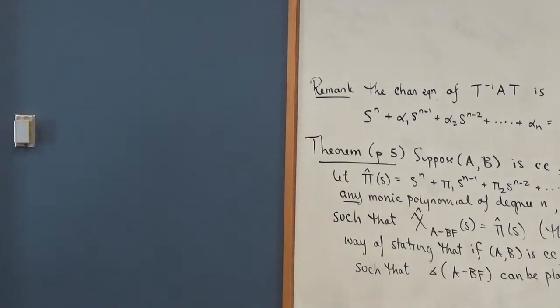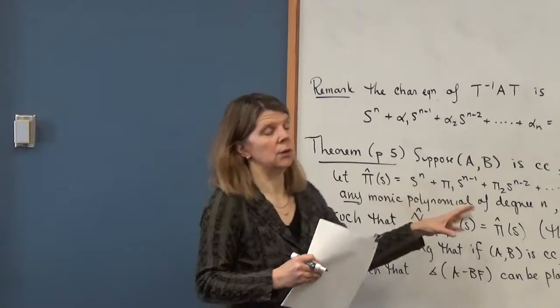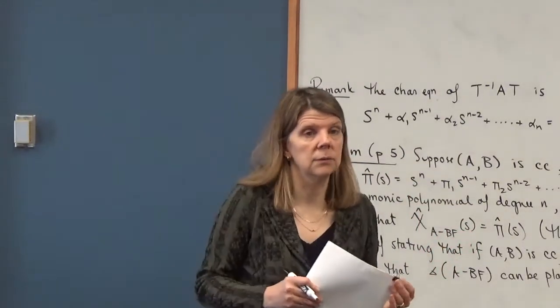Okay, are there any questions now about the process of designing this F, or the result that if the system is completely controllable, then you can always design a feedback gain matrix F to get those closed loop eigenvalues anywhere?